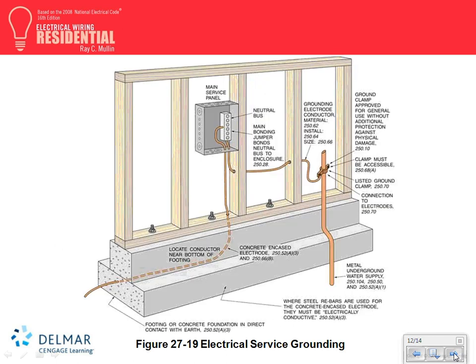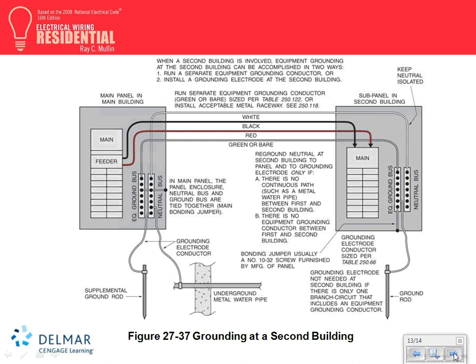Ties bonding. I'm going to move, guys, into bonding. Any question about bonding on the service entrance equipment? On the service entrance equipment, Brooks, my friend, we have to do 2 things. Number 1, we have to bring a grounding conductor to the Mother Earth, to a rod, and to the pipe. We have to bond them. That's number 1. Number 2, we have to bond them together with a loop.